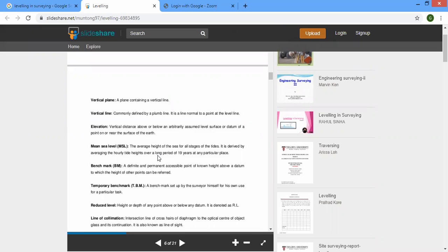Sometimes, if you are going for surveying in railway station areas, on railway platforms the levels will be written with respect to mean sea level. You can check the board of that railway station. There you will have the permanent benchmark which has the known level with respect to mean sea level, right?